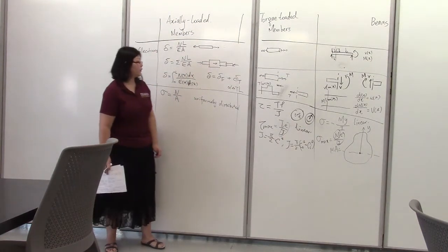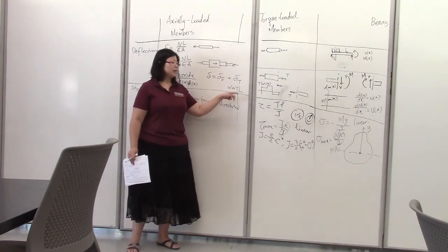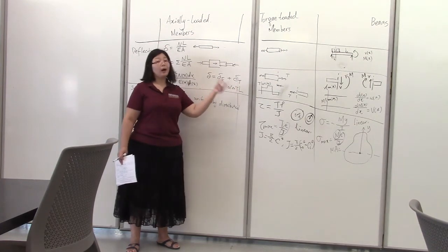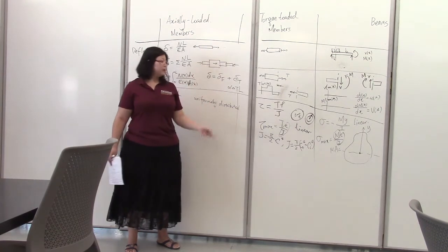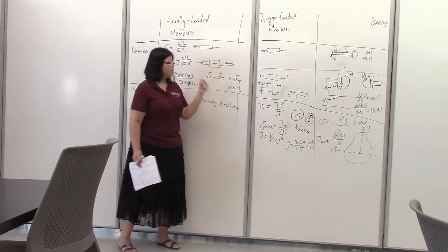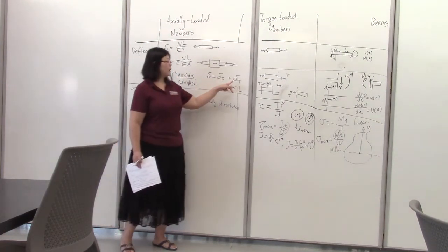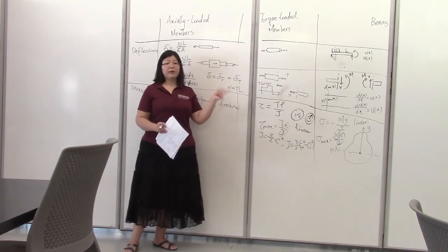It's the linear coefficient of thermal expansion. So delta T could be positive or negative, which will make this delta T term positive or negative. If the temperature is increasing, we have a temperature increase, then delta T is positive. Otherwise, when delta T is negative, we have a temperature decrease. That would cause the segment of the bar to contract due to the temperature effect only.